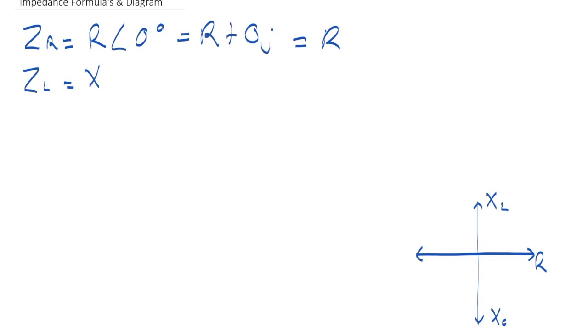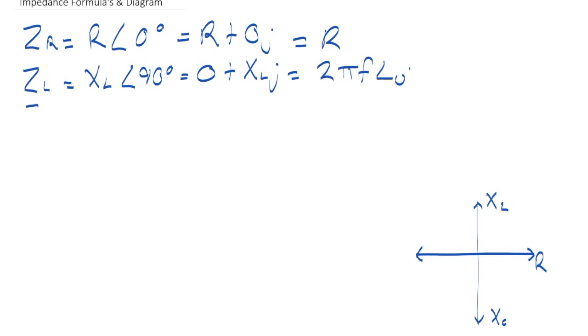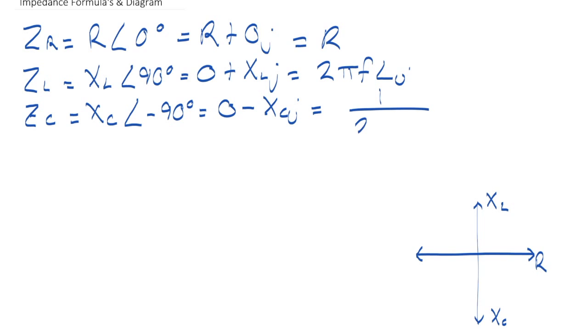They are shown in both polar and rectangular forms, and there is also the breakdown of the inductive and capacitive reactances. These impedances are represented by an impedance diagram, which is shown at the bottom right of the screen. The axis that each impedance lies on corresponds to the angle of the impedance in polar form. The inverse of impedance is admittance, which is a measure of an AC circuit's ability to allow current to flow.